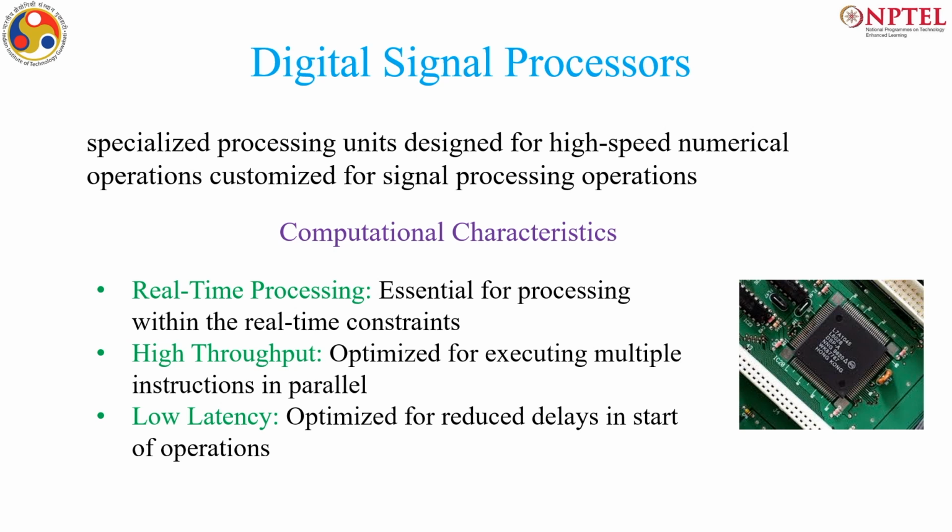So, here we are more interested to learn about the signal processors, DSPs. As the name suggests, these are specialized and customized for signal processing applications. And there are three things which are taken into account for designing DSPs. First is real time processing, which means that it should work within real time constraints. Say for example, you are shooting a video and your audio and video are not synced, that will destroy your purpose. So, the real time processing constraint should be there, it should work within the time.